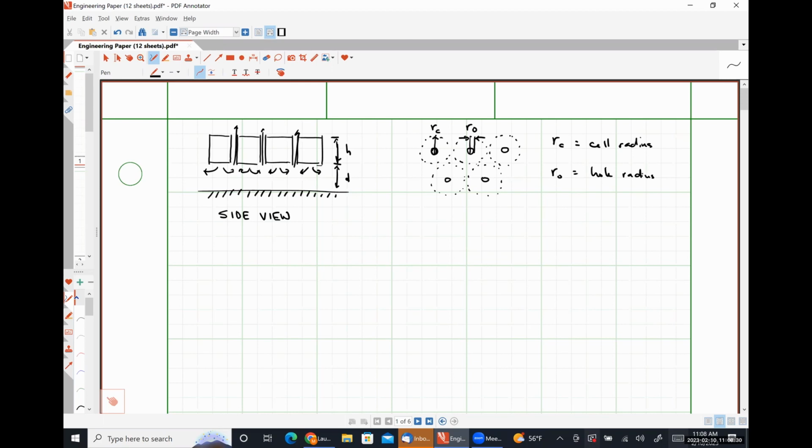If the plate is very thin, the air that's passing through the plate will not encounter any large amounts of flow resistance through that channel. And so we'll have one particular damping coefficient. If the height of the plate or the thickness of the plate is very large, we should see that the flow resistance of those individual channels dominates the damping. And so we're going to have a particular damping coefficient for that particular configuration.